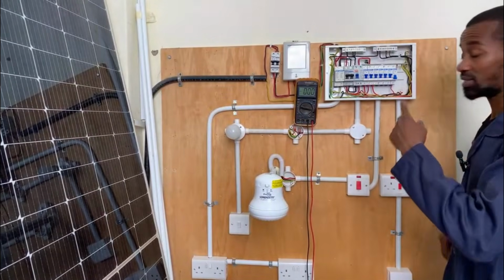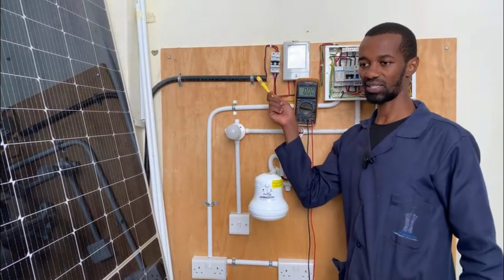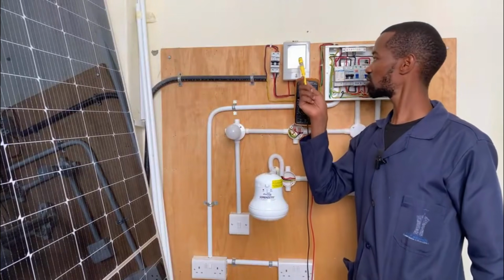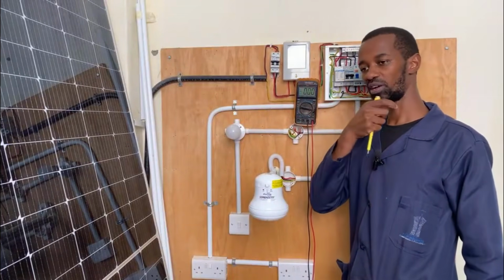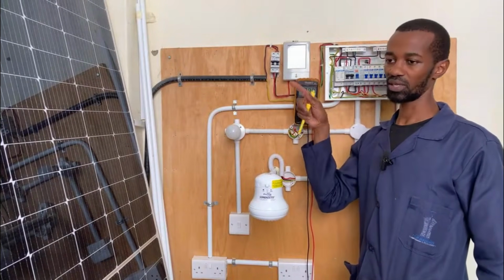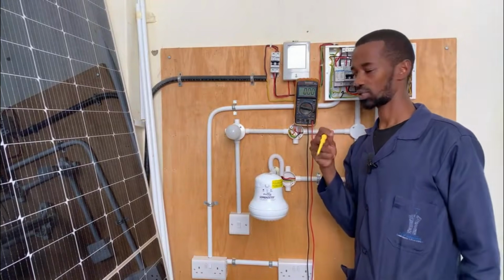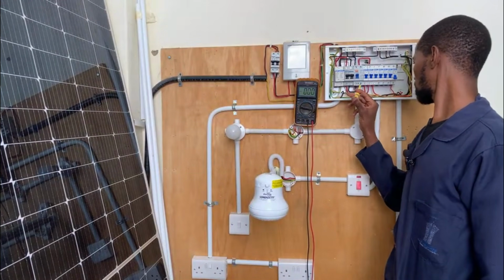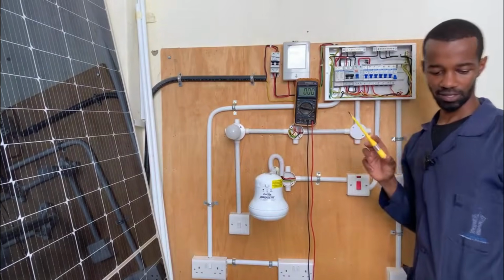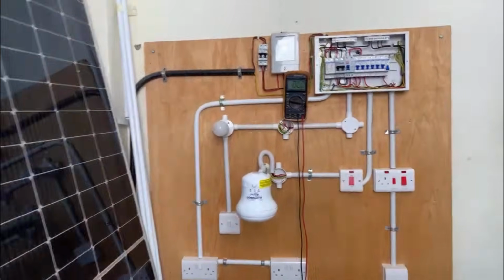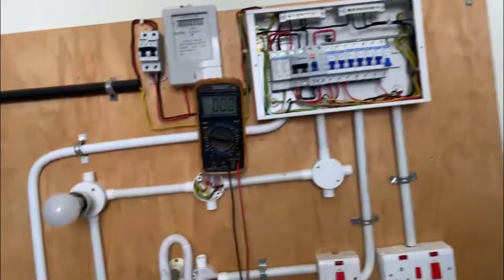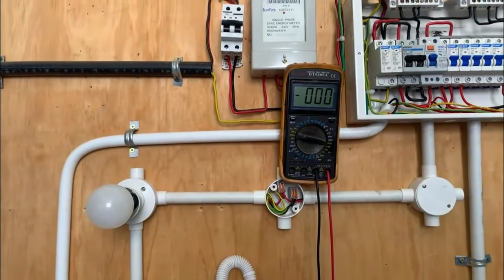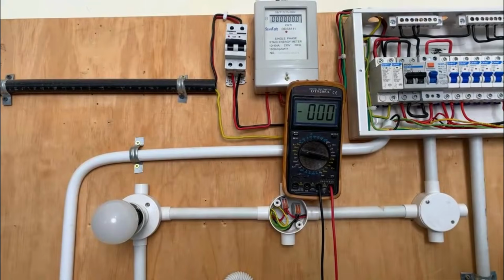Now I have corrected that by simply reversing the connection that was incoming here. That was very dangerous because this one is a digital multimeter. It could have damaged my meter. So I'm feeding this source from the socket. I had reversed it, so the neutral does not have a connection, but the phase is indicating. So let us just go and confirm that. If you'll be watching this video later, you can simply skip scenes and confirm that we actually fixed the problem.